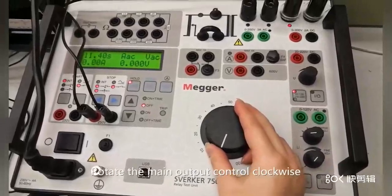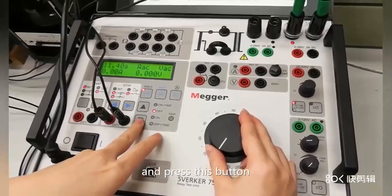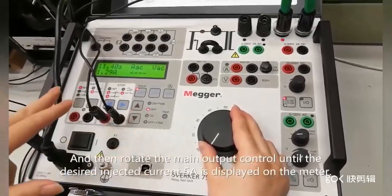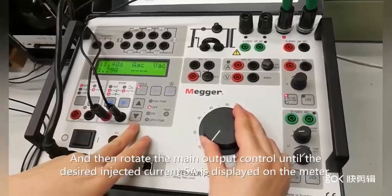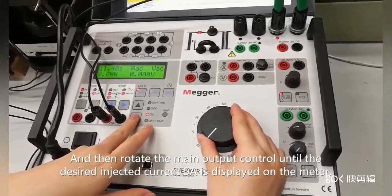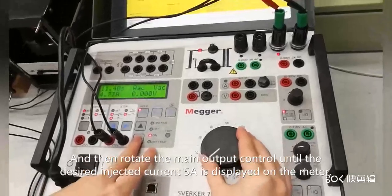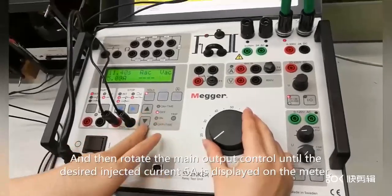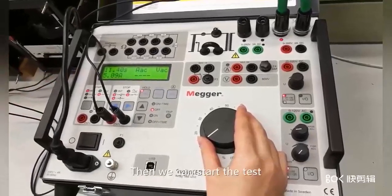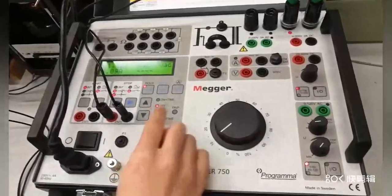Rotate this switch and press this button. Then rotate it until it's near 5 amperes. Then we can start the test.